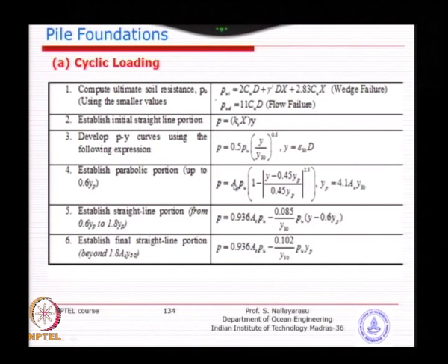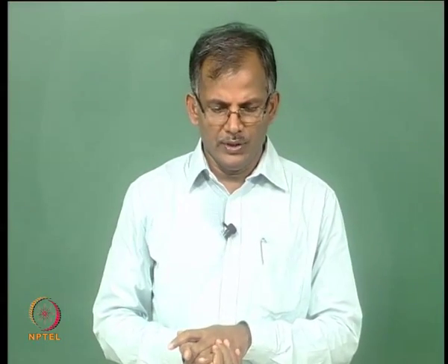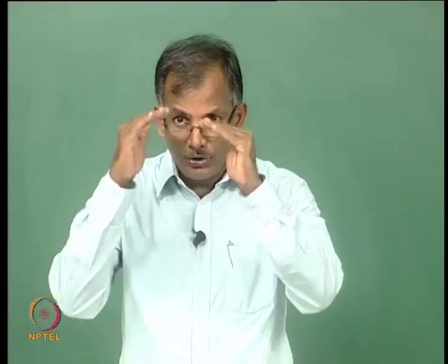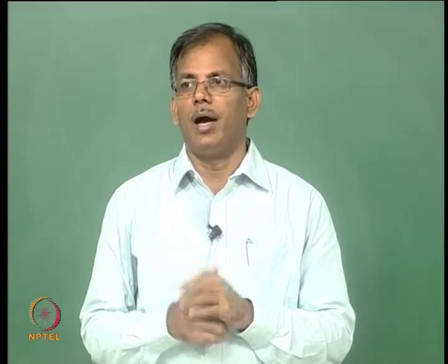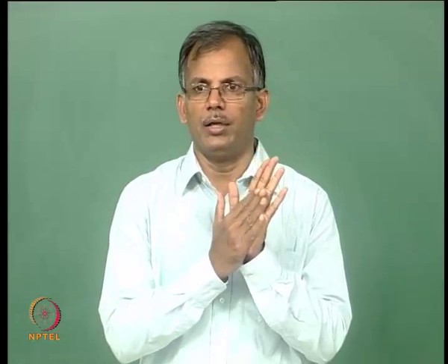So, the only difference between soft clay and hard clay is that the shape of the p-y relationship is almost curvilinear, and the values definitely will be lower. It has to be lower, because we know very well that even though the strength of the material is good, because of its nature the soil is not going to stay in touch with the pile.